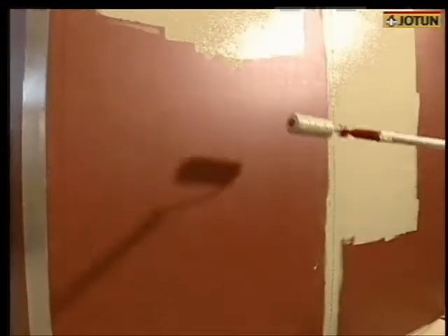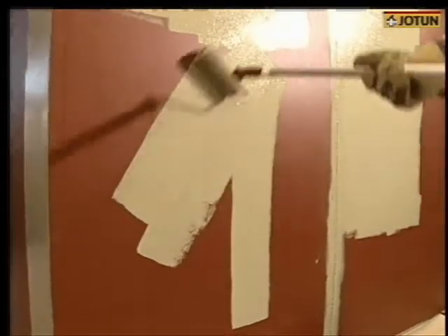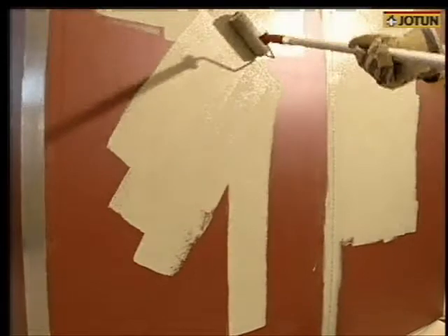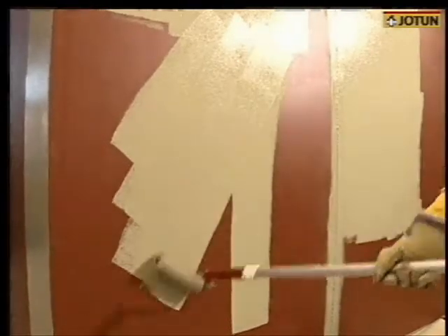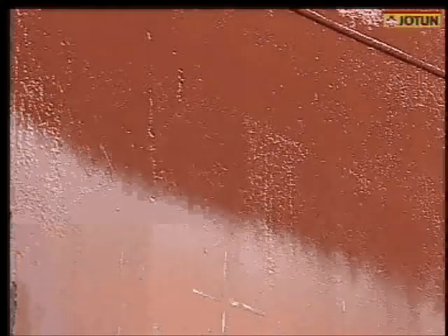When working with an extension, more or less the same procedure should be used. Apply 1 or 2 stripes of paint with the roller. In many cases, the cross-rolling has to be carried out in a diagonal direction rather than at an angle of 90 degrees to the initial stripe of the paint. Remember to use the same final rolling direction as for the other areas.